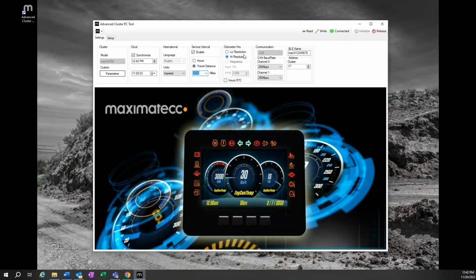The hour meter will have the real-time clock configuration available. During this mode, the hour meter will count the time from the RTC internal module. The trigger for this counter will be the RPM value from the input that's configured as the tachometer input. So we can check that here.